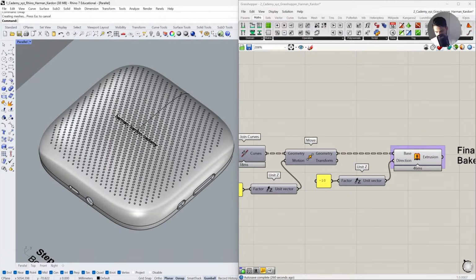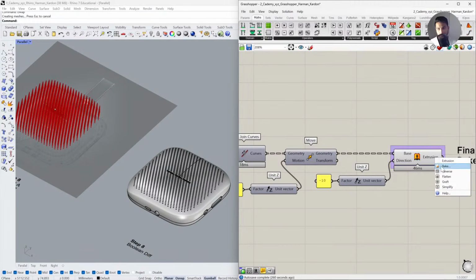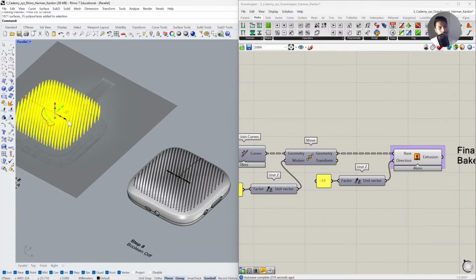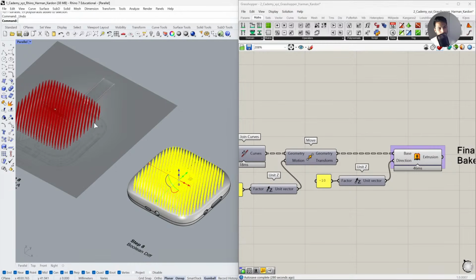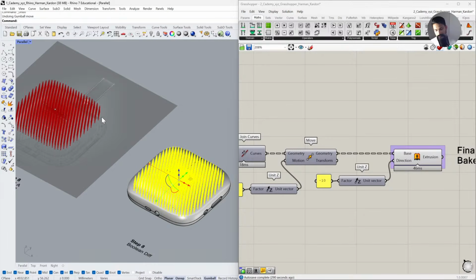Missed the Boolean when you shifted us to the final bake. So once you bake the object, group it, and you move it by 200 units. Okay, so you click on the gumball and you can move it by a fixed amount, 200 units. Okay, the arrows you can either drag it, but if you want a fixed value, click on it, and then